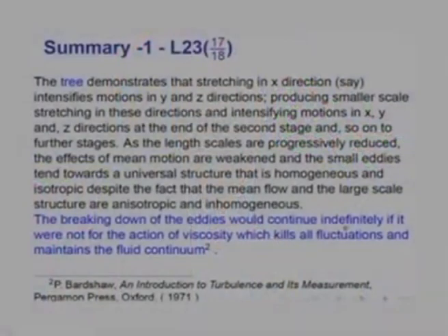And therefore, there is no question of continuum being brought under question. Continuum indeed prevails, as the analysis shows, at small scales in turbulence. And therefore, as we showed here, the breaking down of the eddies would continue indefinitely if it were not for the action of viscosity, which kills all fluctuations and maintains the fluid continuum.